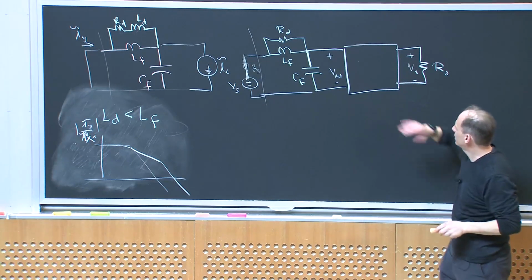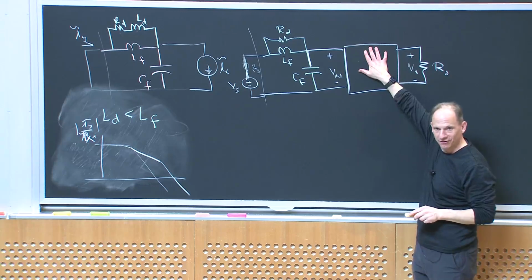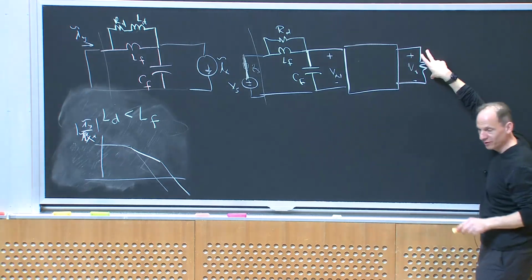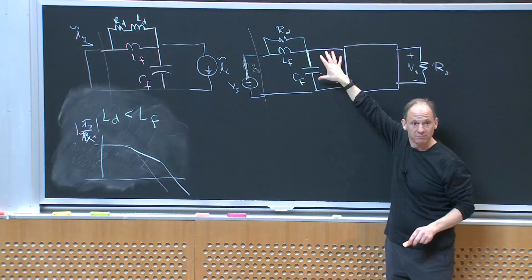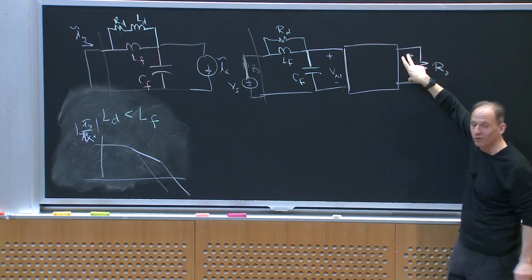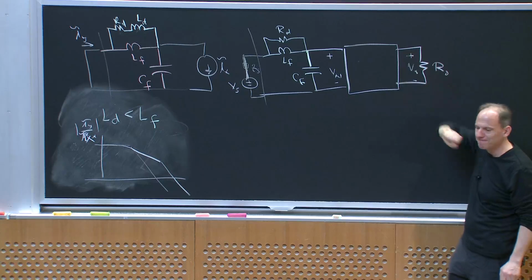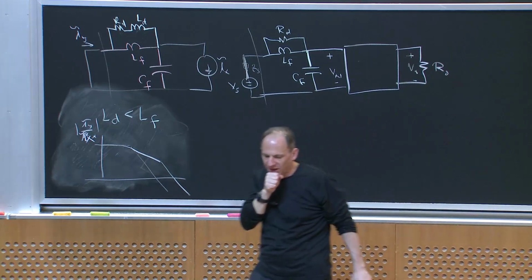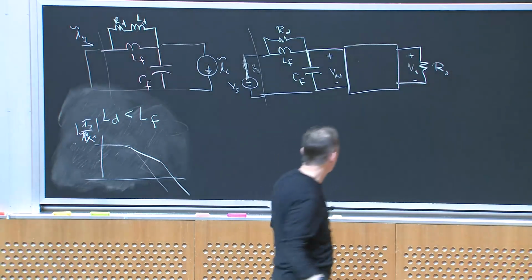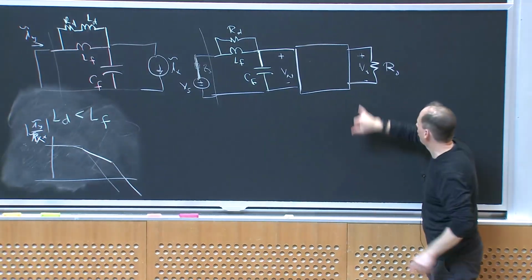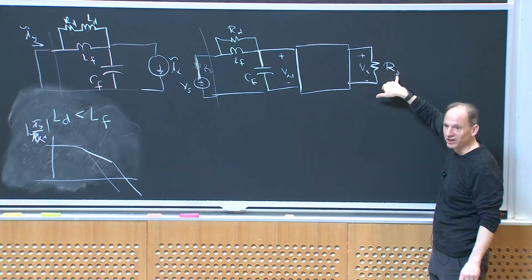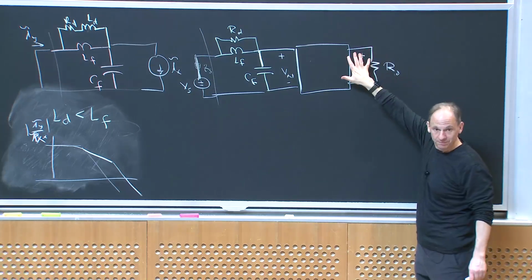All right. What does this power converter do? Let's assume he's a perfect power converter. He's going to keep the output voltage at the reference no matter what the input voltage does. Right? That's his job. Input voltage varies, I don't care. I'm going to keep 12 volts at the output no matter what. Okay? So what would I say that he does? Well, he's a constant power load in that case, right? No matter what the input voltage is doing, I want to draw V reference squared over R naught if this is some fixed load at the output.